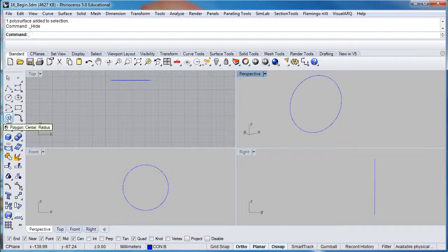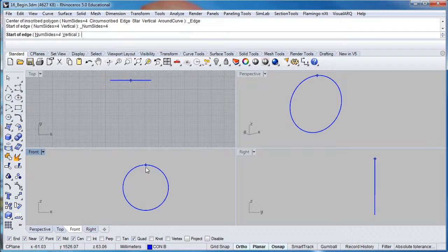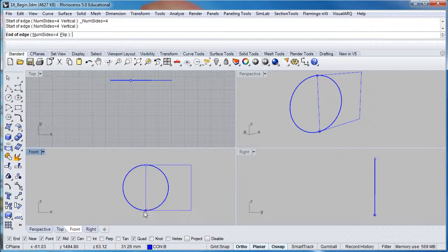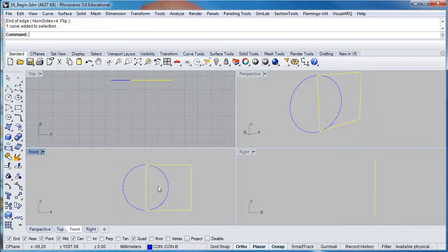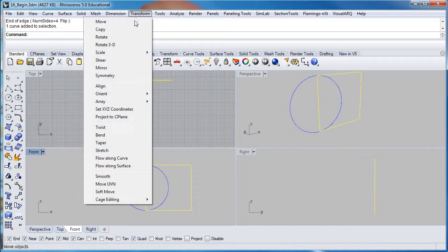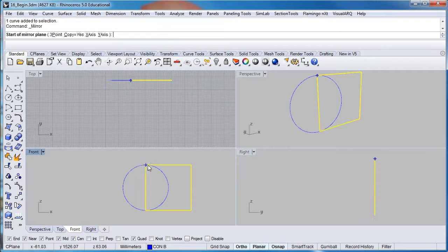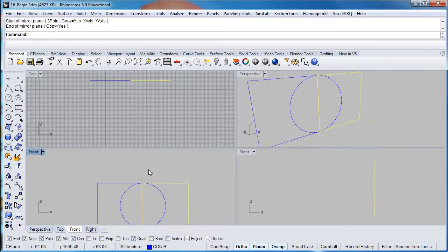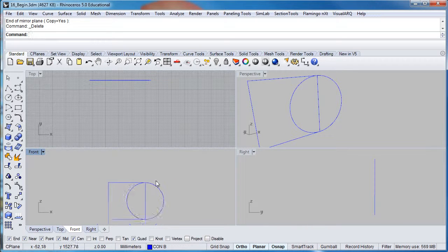So in order to access the square, we go under the polygon command on the blue triangle, and you can see square by edge. The snap that we want is quad, so we're going to snap the top edge of the square and then down on the bottom edge, and we're just going to mirror that across. So once these things fall in position, often they'll flick the opposite way, so we just transform, left click on mirror, just drag to the top, and we've reversed that. Press the delete, and now we've got everything in position.